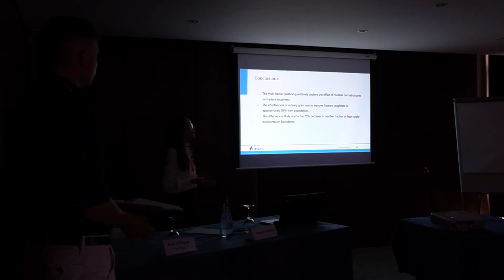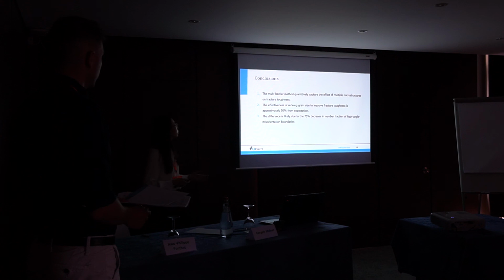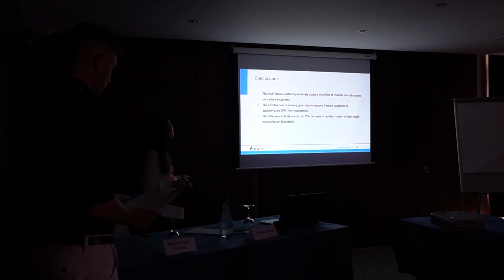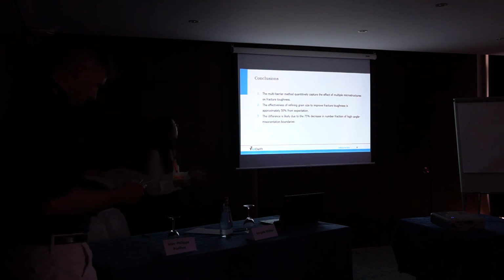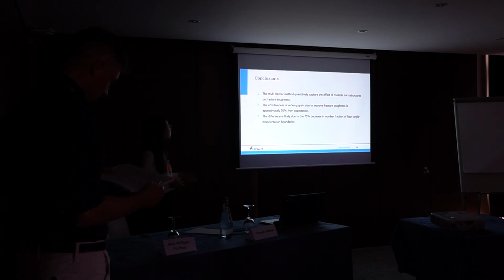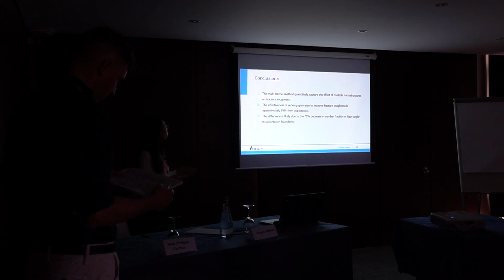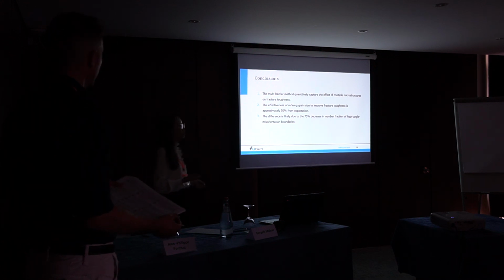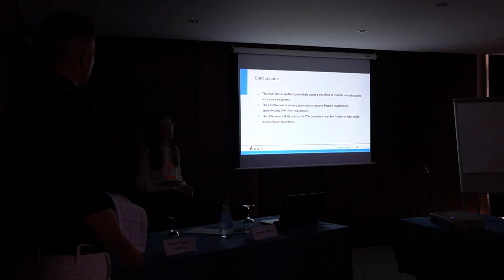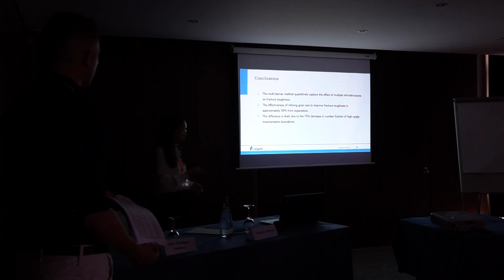It is not so direct to quantitatively model the fracture toughness purely from the block and packet boundaries. So we are still working on finding a way to represent the effect of those substructures by using this model, perhaps through the cleavage parameters that we define for the resistance of those boundaries.